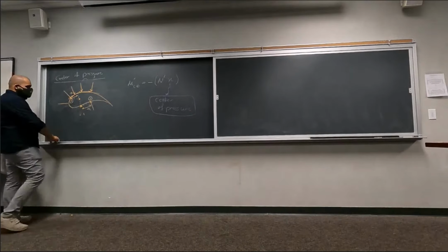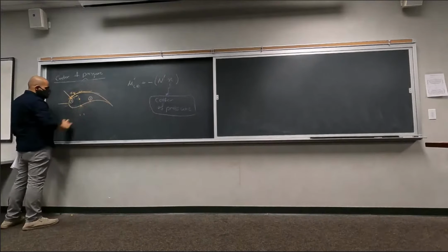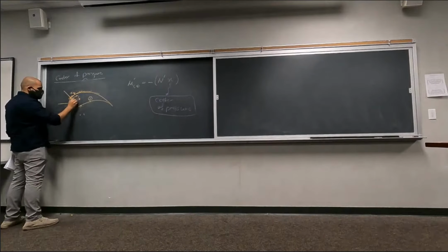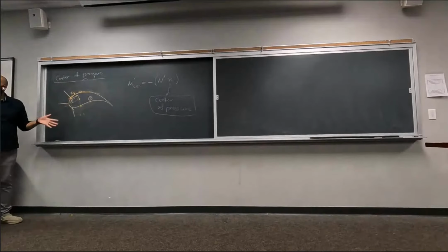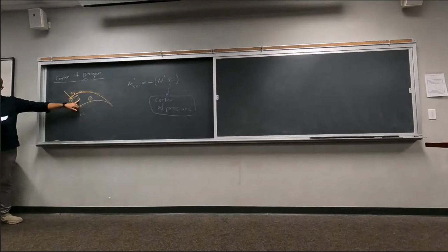Let's say we only have these two pressures. Let's say we have a pressure here, this arm is exactly the same. The only difference is going to be the direction of pressure. They are going to be applying two exact same moments at different directions, right? Which means that you're going to get 0 moments here. That's the idea of center of pressure.